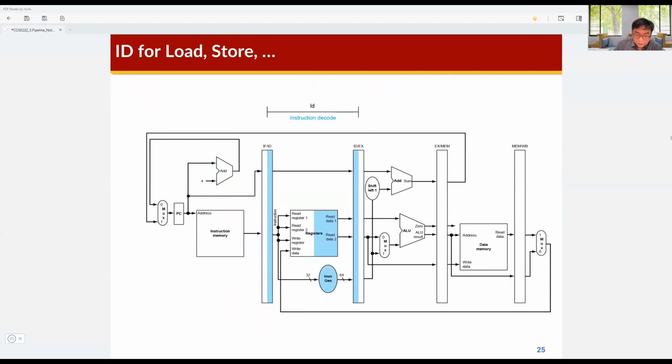So during the next clock period, this instruction data is delivered to the register file. Also, the PC is delivered here. So this is the instruction right after the rising edge of this clock.